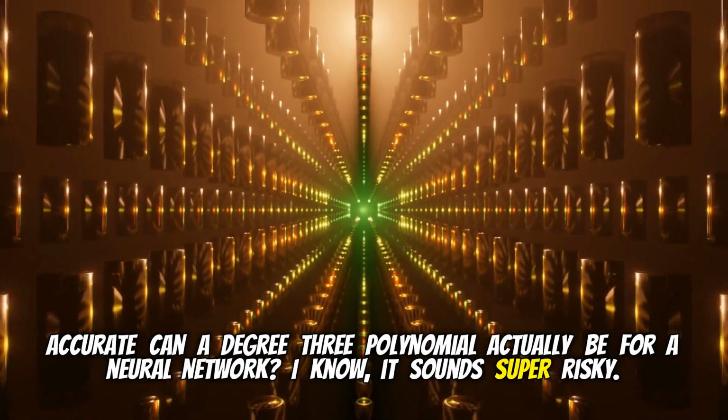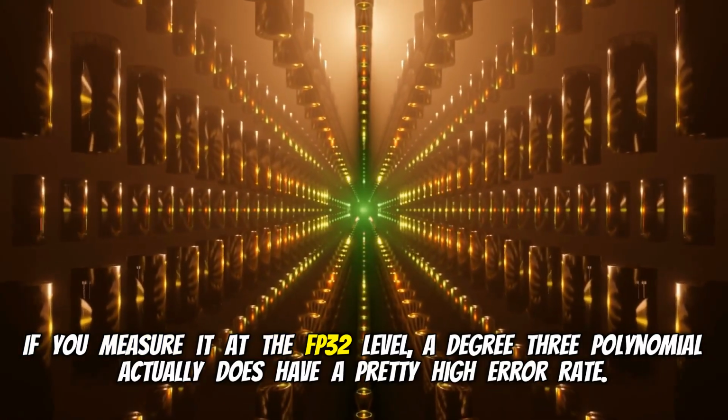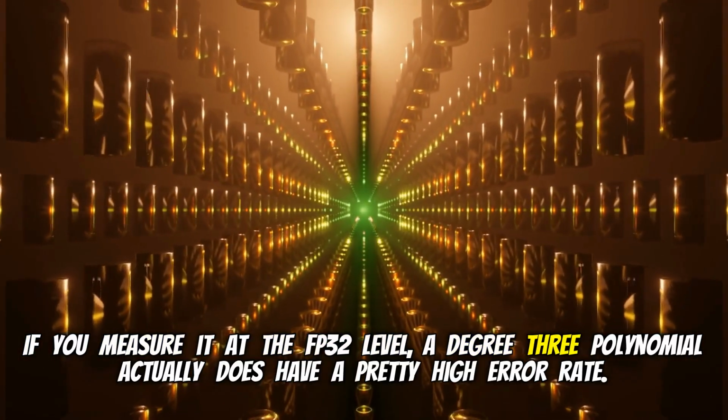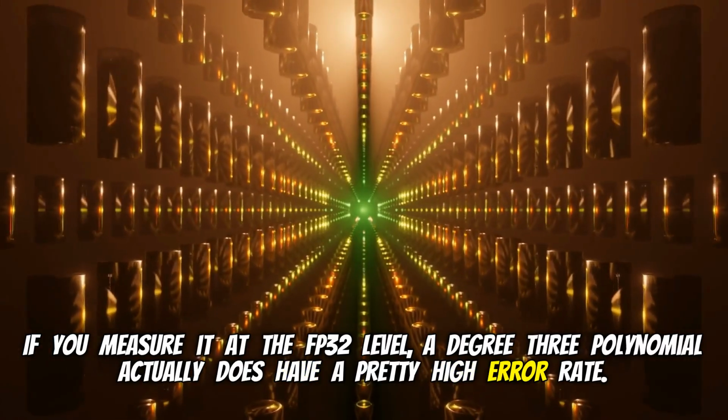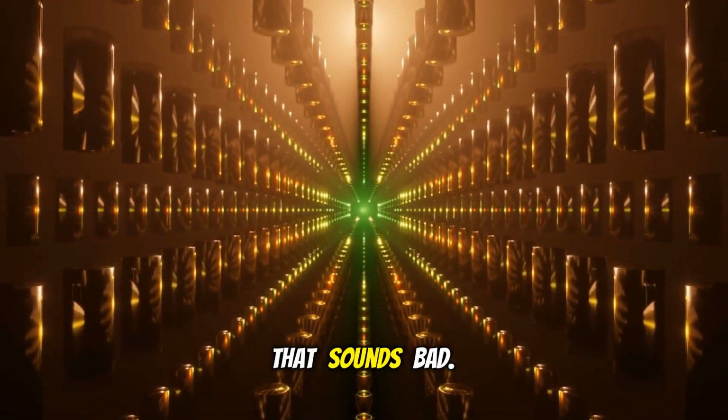I know, it sounds super risky. But the paper has all the data on this. If you measure it at the FP32 level, a degree 3 polynomial actually does have a pretty high error rate. It's like 600 times higher than the dedicated hardware instruction. That sounds bad. It sounds terrible.